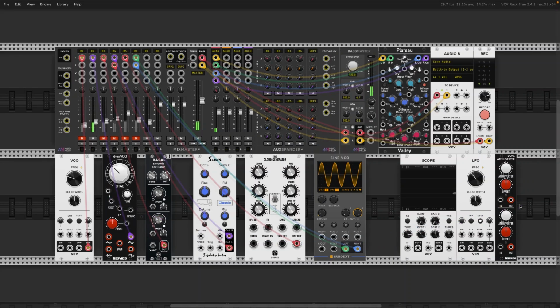What am I doing here? Let's take the triangle wave again in here. And now we're going to control what's happening between this and this point. And we're going to feed this into the volt per octave input. And nothing is happening because the Atenuverter is not open.